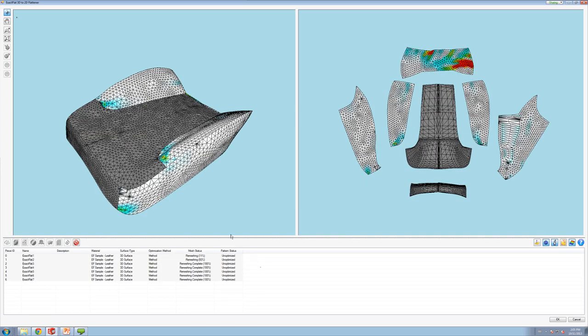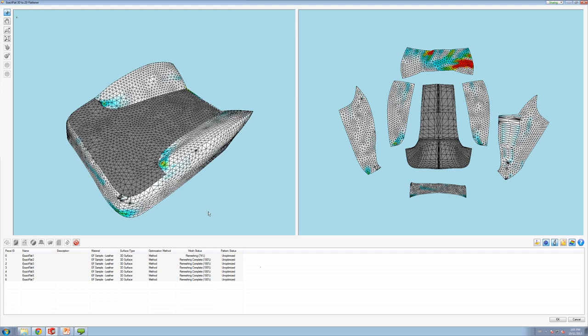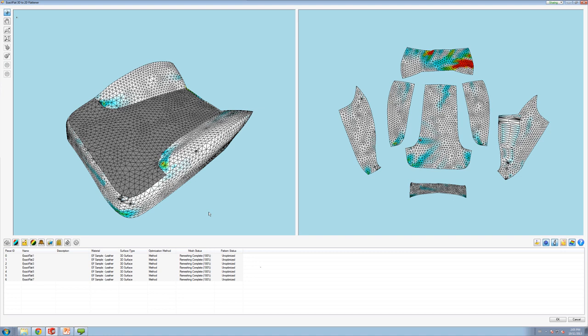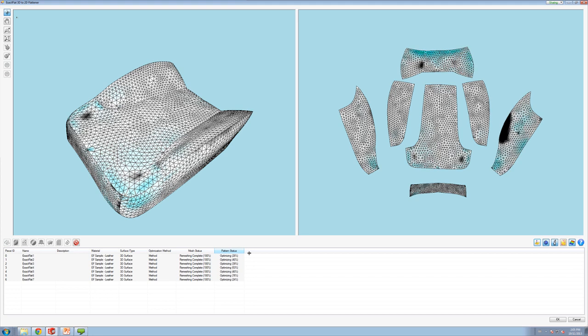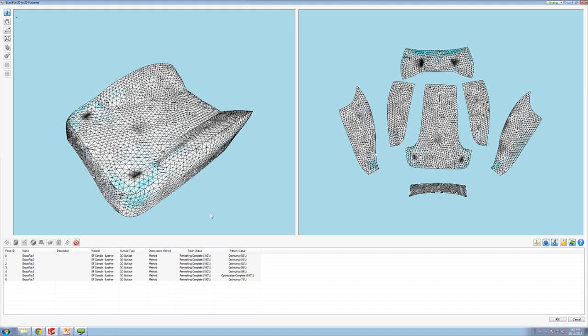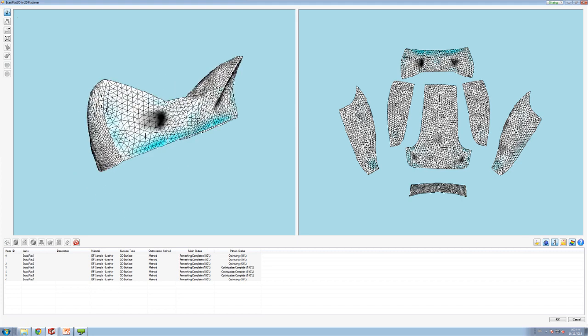And you can see that it's roughly drawing the mesh elements in proportion to one another such that they're the same size. And it'll just take a second or so. When the meshing process is complete, we simply click Optimize, and it'll go through a process of searching for strain and sag. That's excess material is sag, and strain would be where the pattern pieces are going to have to pull tight. And it's going to try and eliminate them.